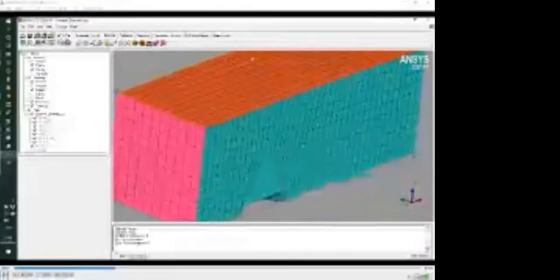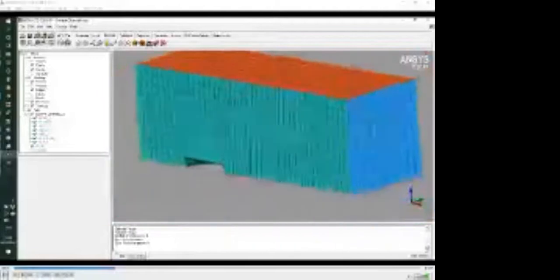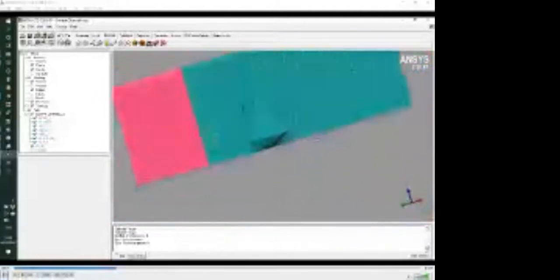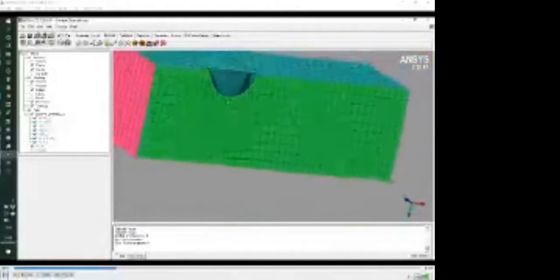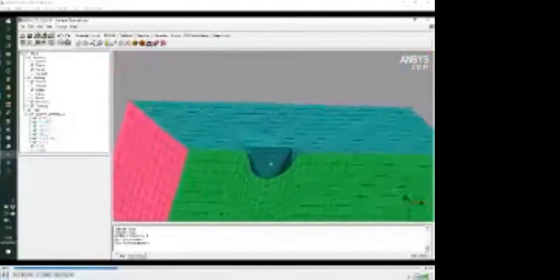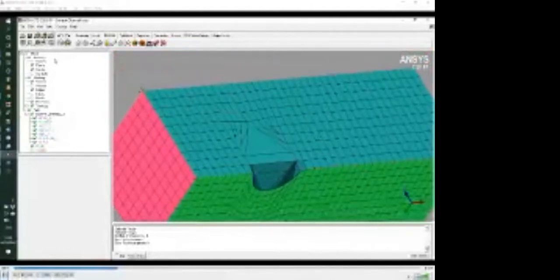You can see how the mesh spacing has been transferred to all the parallel edges, which is very convenient. And it's even made some attempt at capturing this bump. It's not great though. That's not a valid mesh. If you put that into a CFD solver, it will dismally fail. So we have to improve on this a lot.